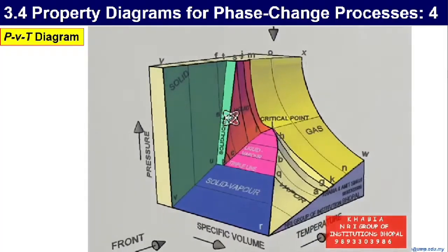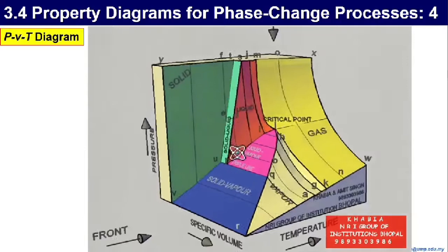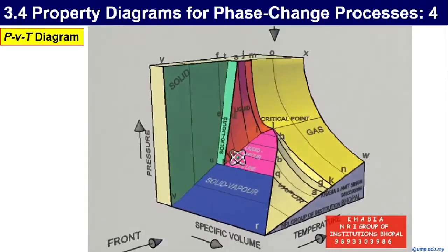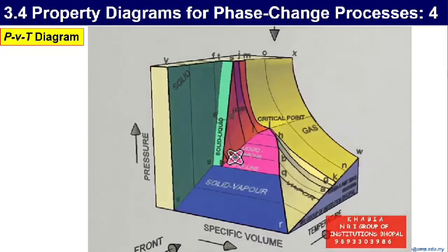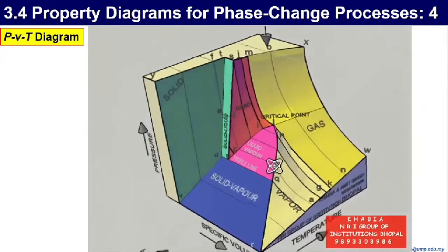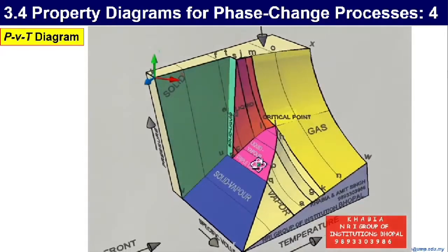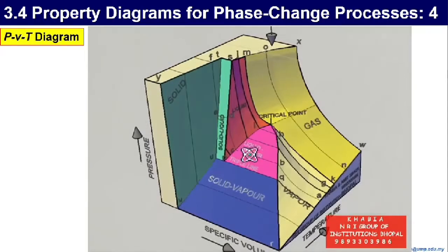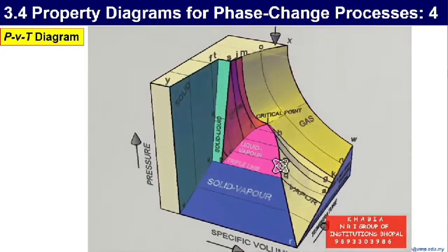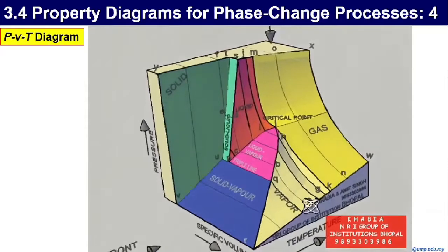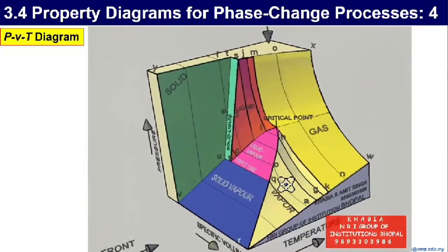On further decrease of pressure, there is very little increase in specific volume until state C is reached. CB is constant temperature, constant pressure vaporization process in which change of phase from liquid to vapor takes place. B to A represents superheated vapor region.